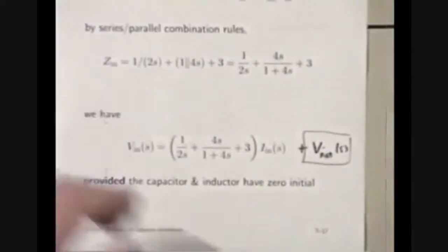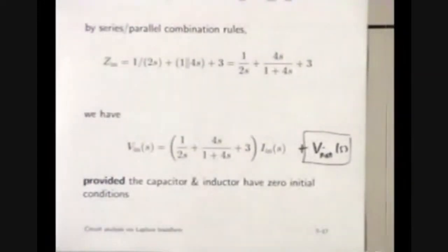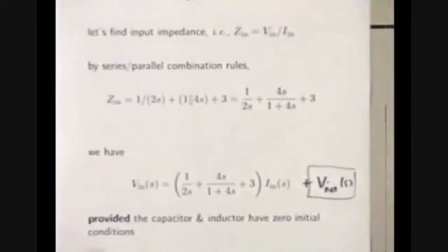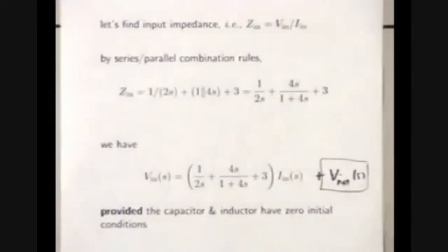Okay. And in fact, this is probably the trickiest thing here, to get straight the difference between when you have an impedance and when not. What is absolutely wrong is the following: when you have a non-zero initial condition, to even imagine that there is an impedance description. There never is. There's no such thing. Right? It's an additive term.